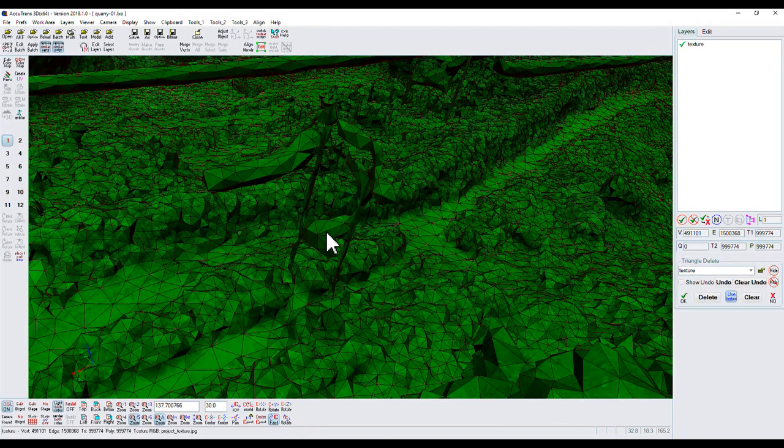Now I'm going to hold down the Shift key and click with the left mouse button, and it'll all turn red. And if I had left one triangle edge from this part that I wanted to get rid of connected to something in the green mesh, there would have been a really long delay as all the triangles got selected in the whole model. So we want that, and so if I just go ahead and say delete, and there it's gone.